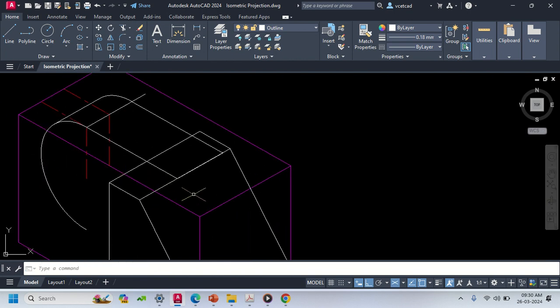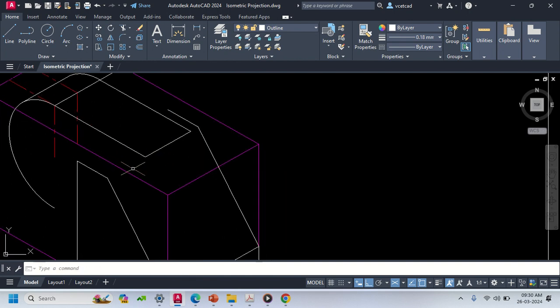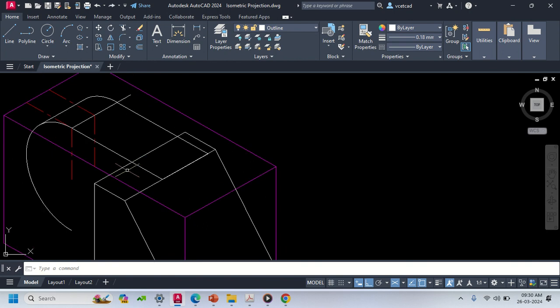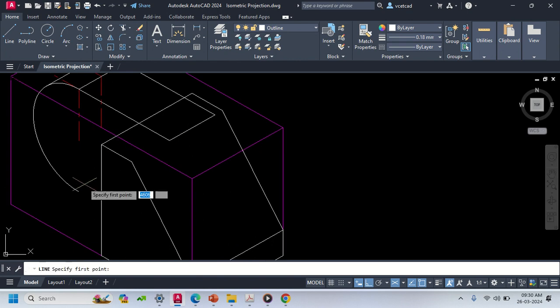Now, this portion, I will delete this line, even delete this line. For instant, I will not keep that line. Again I'll undo. This line is overlapping, right? This line as well as these two lines are over. So you can hide it or delete that line. Similarly, L enter. From this point, I will draw a line. Will end at this point. TR double enter. Trim this point.